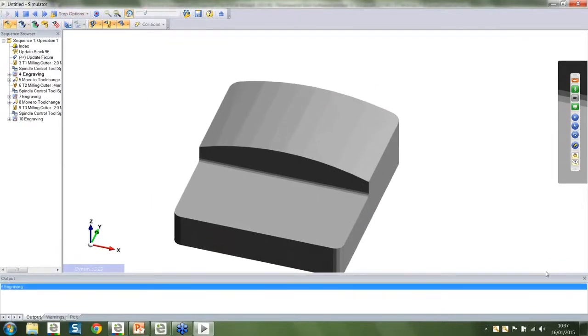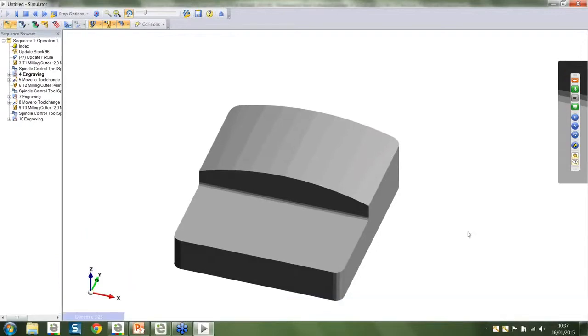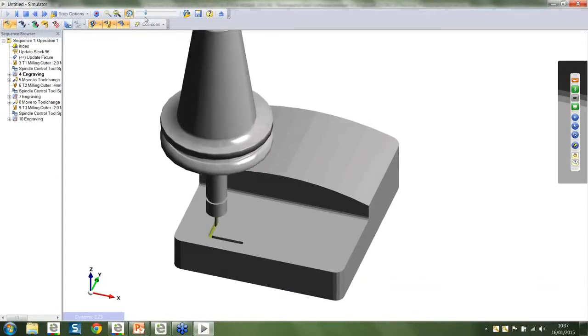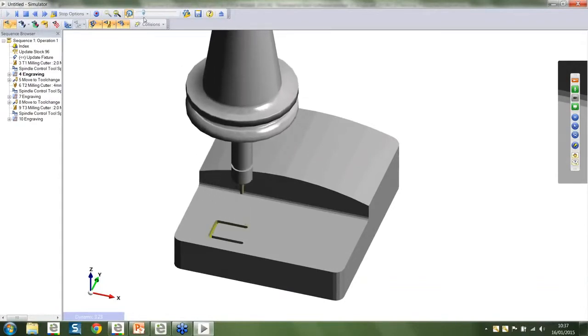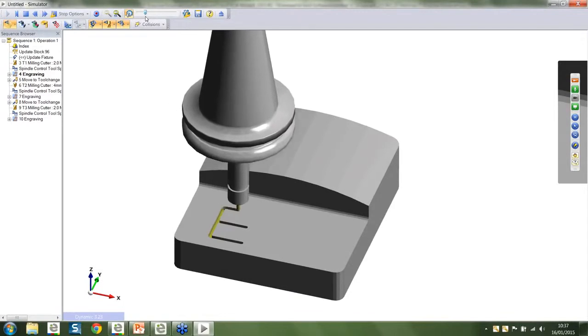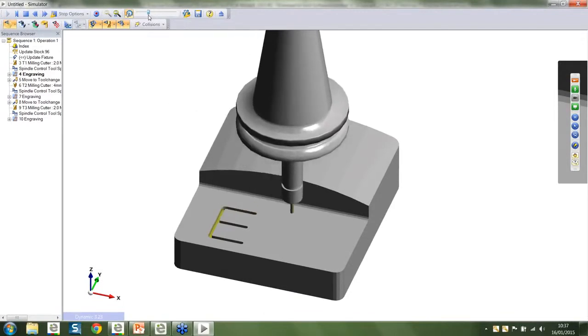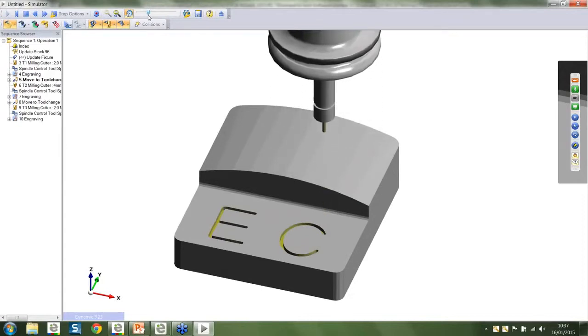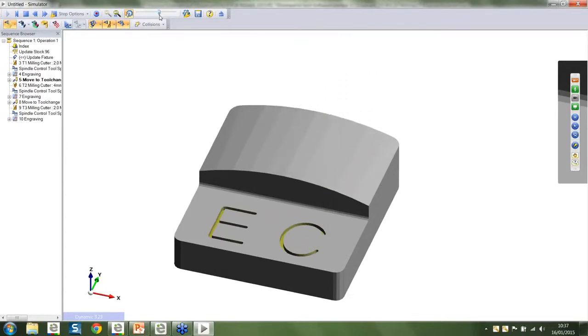All I've simply done is ask the tool to select a center line. And so you'll see now it's just, if you will, roughing out that area for me in readiness for the finishing command to come. So I just digitize the feature. It doesn't matter how complex that feature is, it will always find the center line for us.